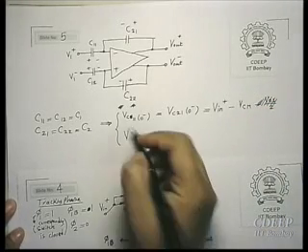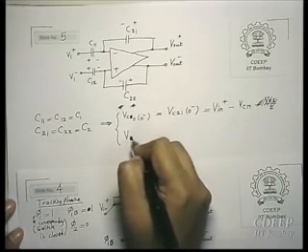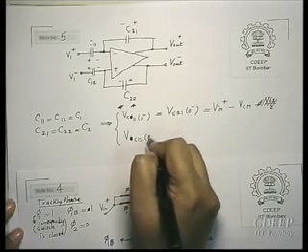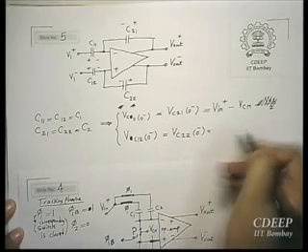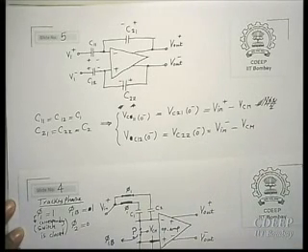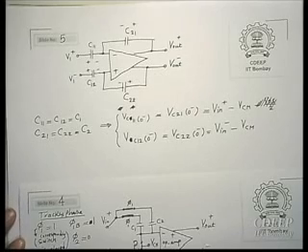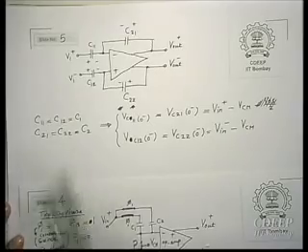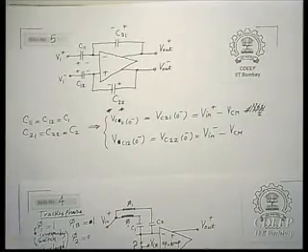We need to keep the Opamp in unity gain feedback. So, and then, okay, VC1, 2, okay, this was the original value which was stored. It was in the tracking mode. So this voltage is now stored here before it goes into holding mode. And then when it goes to holding mode, you will have a transfer of charge from C11 to C21, and of course now these inputs also are connected to V1 plus, V1 minus.